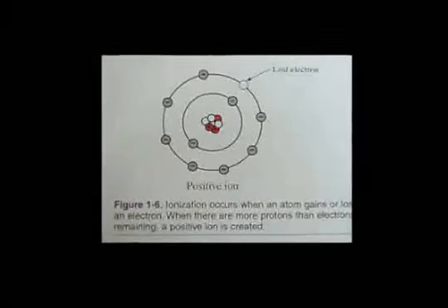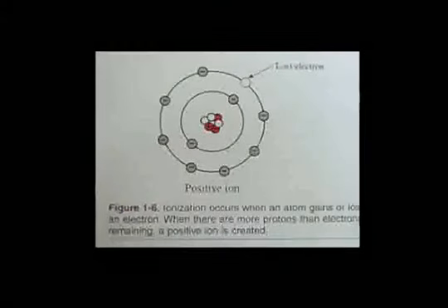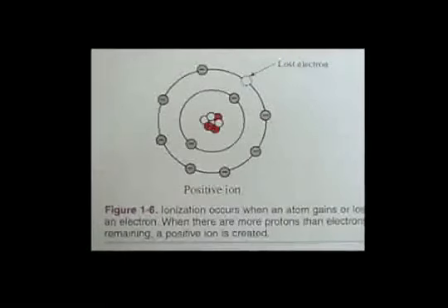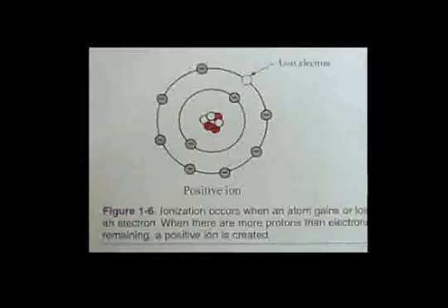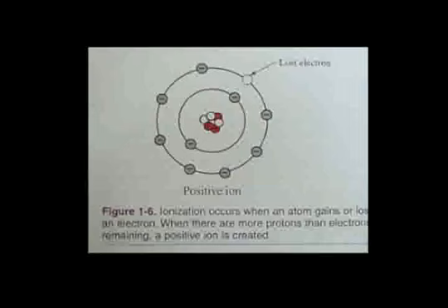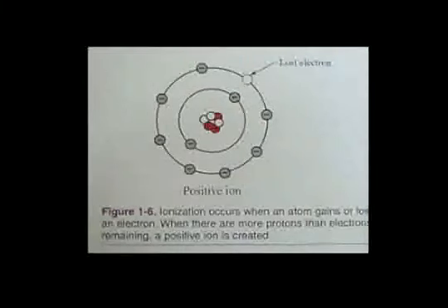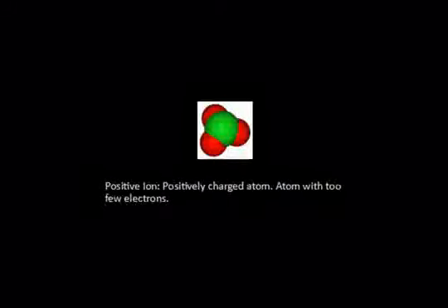This concept is extremely important and will be repeated throughout this book and in your studies of electrical phenomena. When the electron leaves the outer orbit, the atom becomes ionized. Figure 1-6, an ionized atom is electrically unbalanced. An atom that loses an electron from its outer orbit has more protons or positive particles in the nucleus than electrons or negative particles in orbit around the atom. The atom becomes a positive ion and displays positively charged characteristics.